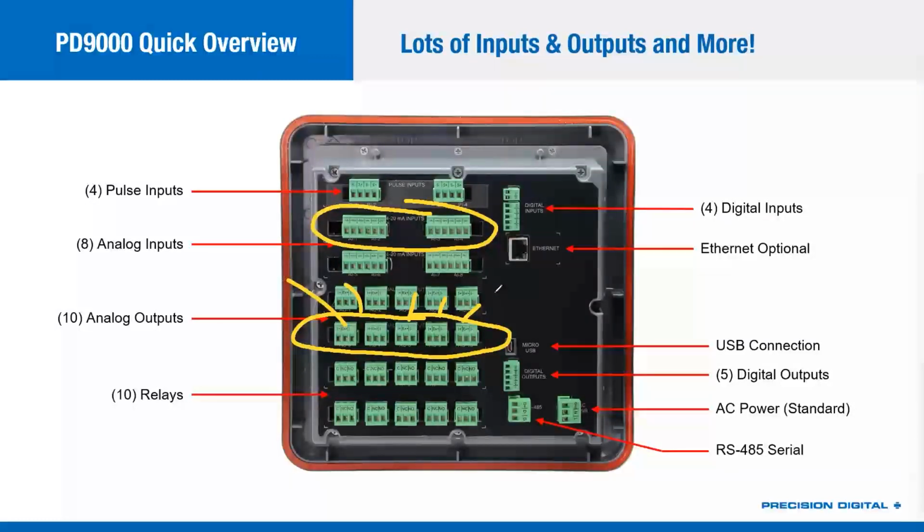So every channel can provide 200 milliamps of power, so long as in total your ConsoliDator Plus is not outputting more than 1600 milliamps of power. So long as you're not going over 1.6 amps of total current being put out of all of these 24-volt power supplies together, you can get up to 200 milliamps out of any individual supply. And I don't know why exactly you're asking, but I will note that is enough to run any 2-wire device, and that is almost enough to run every transmitter out there.